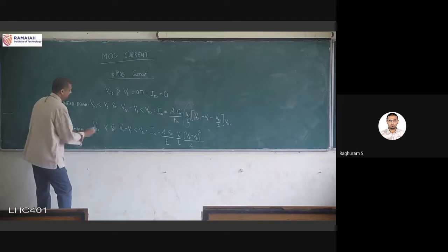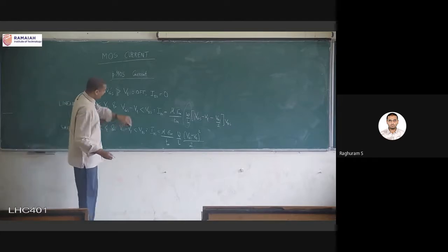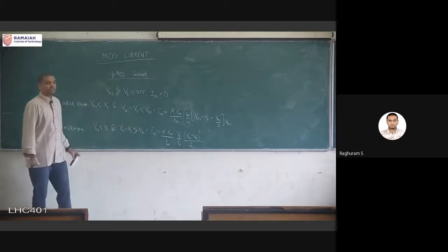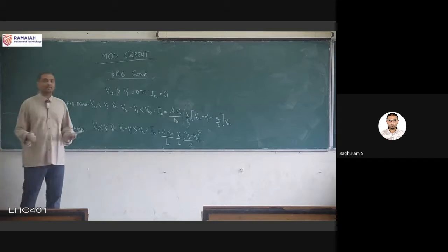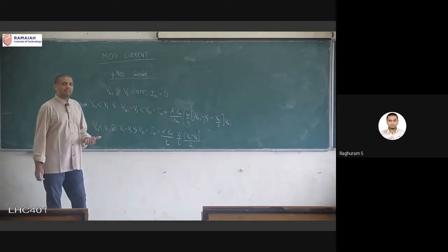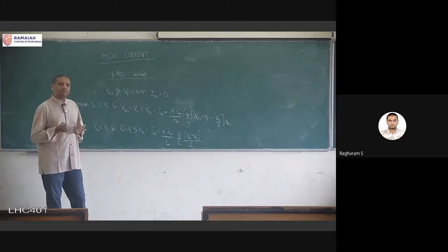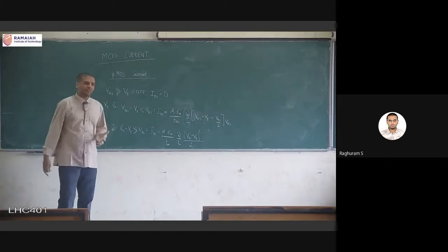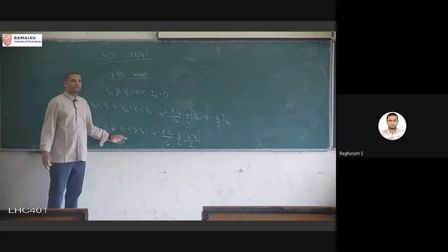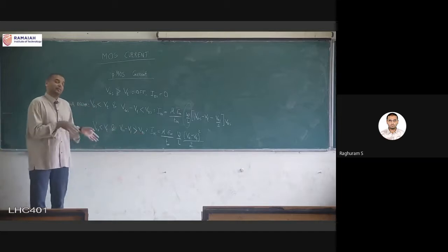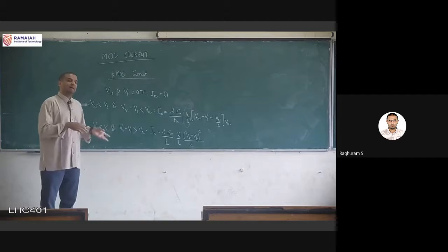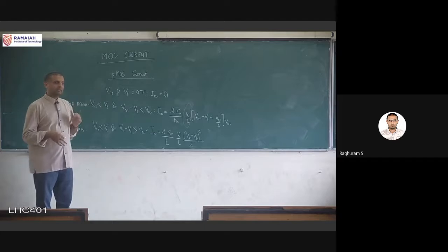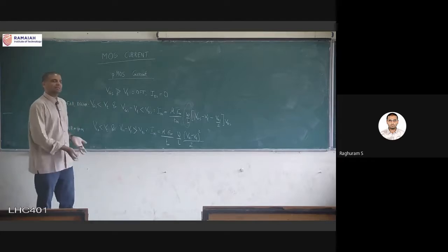Saturation means that it is on, and in addition, VGS minus VT greater than VDS. The reason why it suddenly reverses: in NMOS I said many times, if the value of VDS is low, it is considered to be in linear, and if the value of VDS is high, it is considered to be in saturation. Here it becomes opposite because we are dealing with negative values. The source generally will be at the power supply, so all the others will be lesser than that. So the smaller the value, the more it is in saturation.